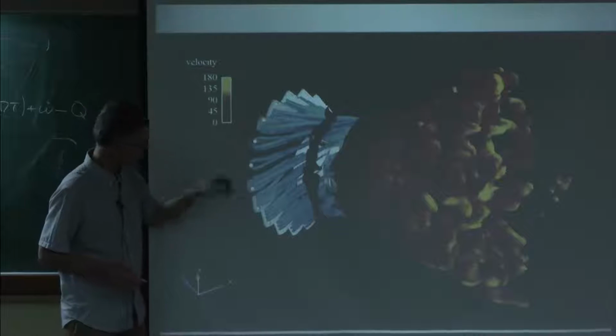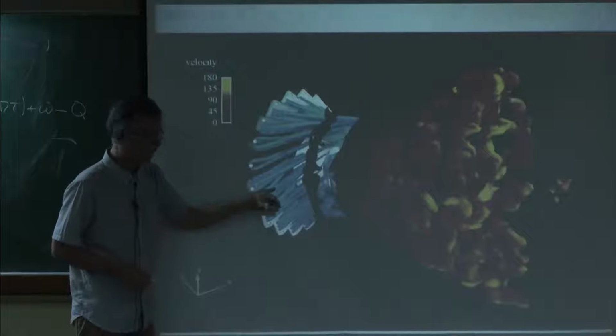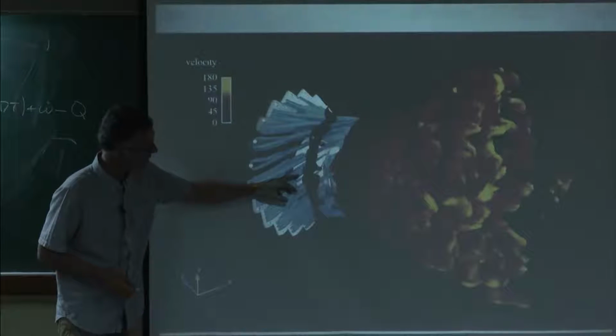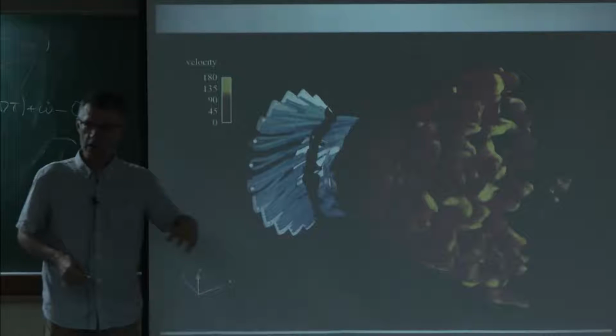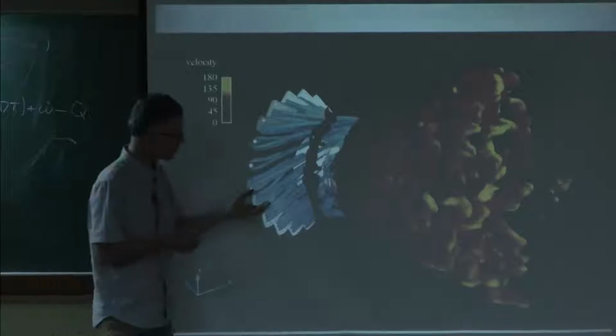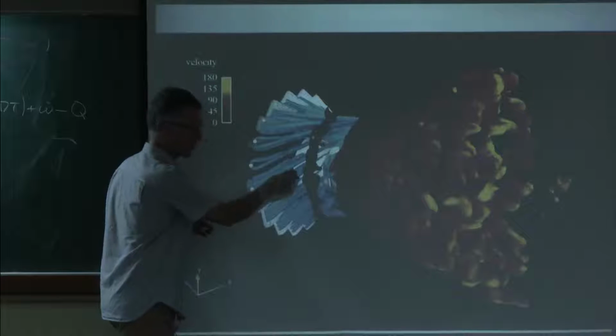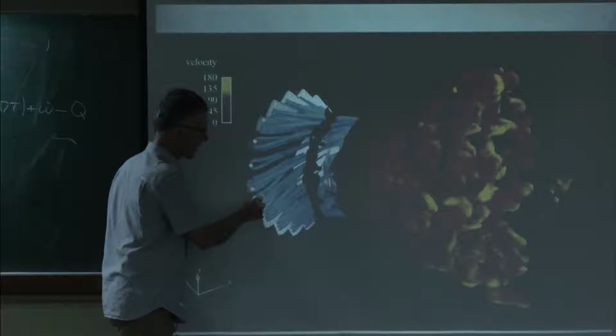So that's a view also of the computation with all the blades at the same time. You can recognize all the jets here. So this is an isocontour of methane, and this is the flame front. And you can see that this isocontour of methane goes into the flame front. If it were perfectly premixed, normally they should be finished here, and you should have a homogeneous value here, but that does not happen. It takes too long to mix, so when it reaches the flame front, it's not perfectly premixed. So you need a model which can account for that. It's probably partially premixed.